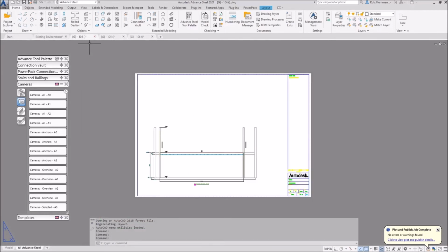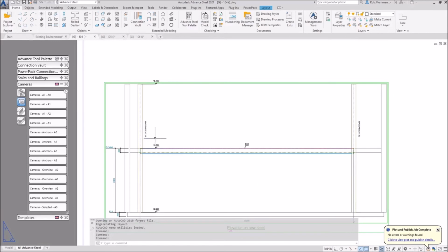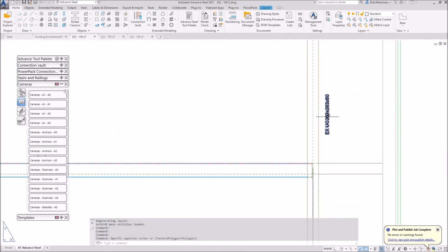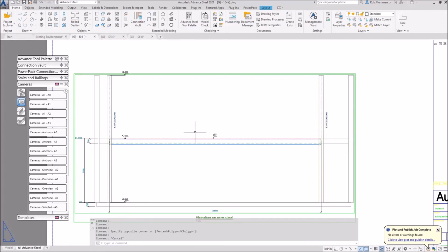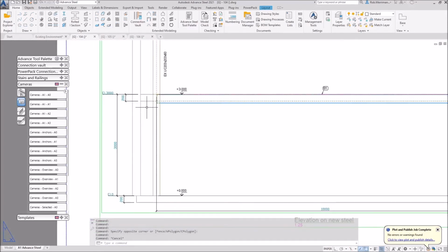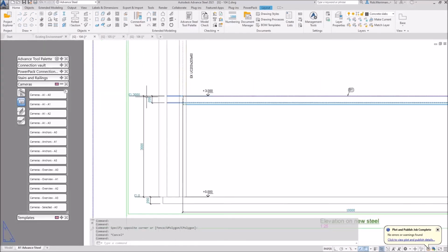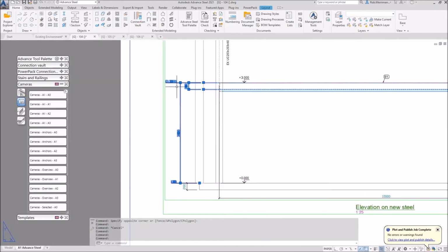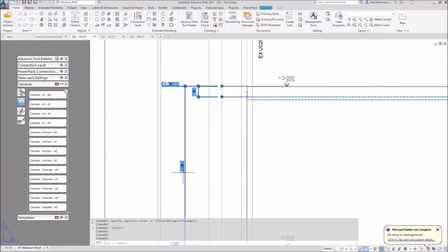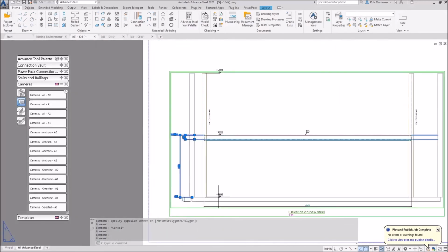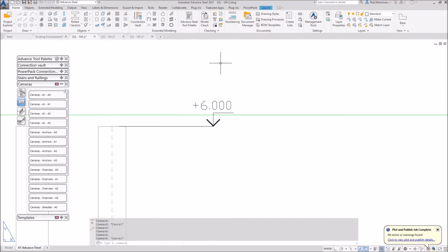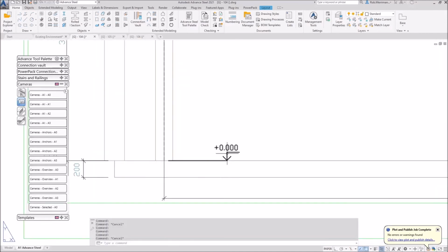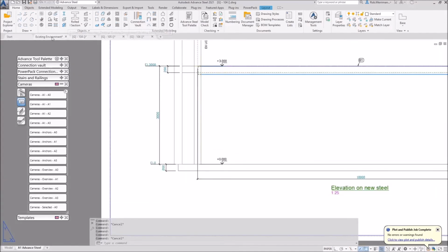The section through the existing steel, again, I've used that existing label to say, right, dimension these as existing. I've also added in a couple of extra dimensions that says if you find a concrete slab, then dimension the thickness of the slab, but also then give me the level information and also the height between the levels. Now, because we've modeled with levels, the system automatically, because we created the levels at the beginning of this webinar, the system automatically will add the level markers for things that it finds. That does only work, well, we'll come back to that in a second.